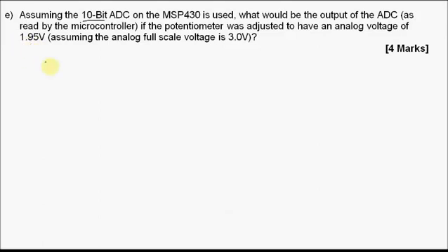So firstly, our step size, we have 3 volts divided by 2 to the 10 minus 1, which gives us 2.93 millivolts per step.